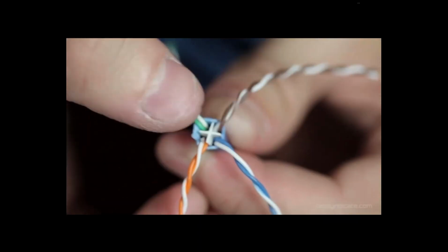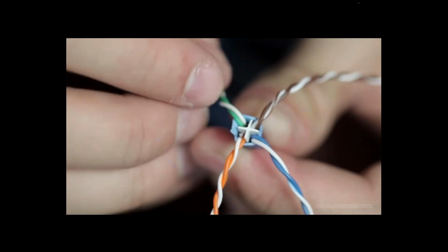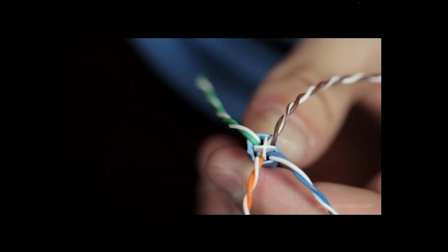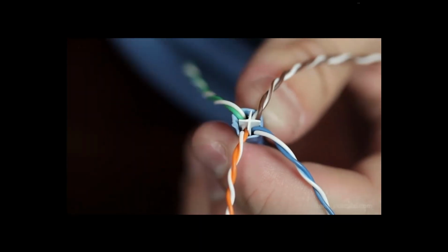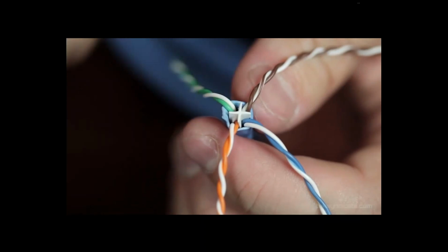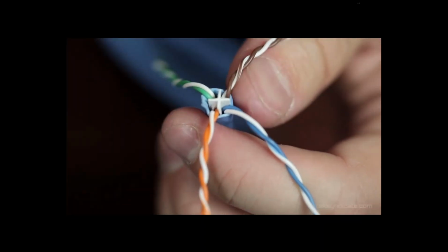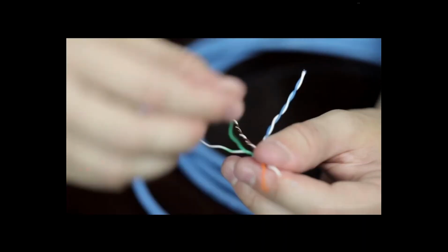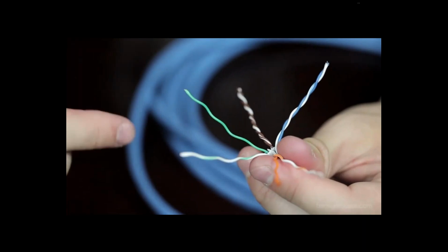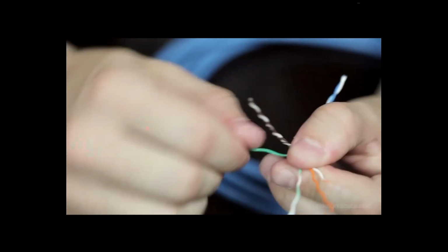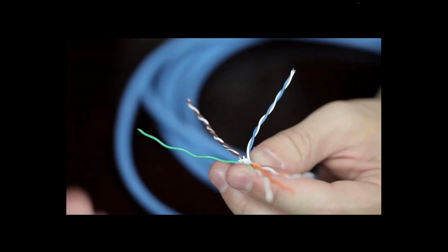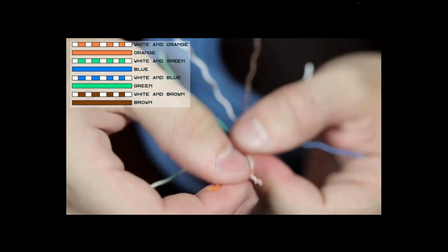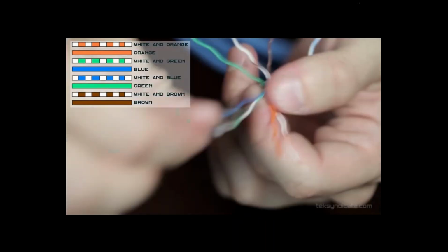If you clip any of the wires and you can see an exposed piece of copper, cut your cable and start again, because that exposed wire will release more noise coming out of the conductor, and it degrades the cable, so your speeds won't be as high as you want them to be. Also, I'd like to point out that these wires are more finely twisted together. There's more twists per cable and per conductor per pair than with the Cat5e, and that's again because of eliminating more crosstalk.